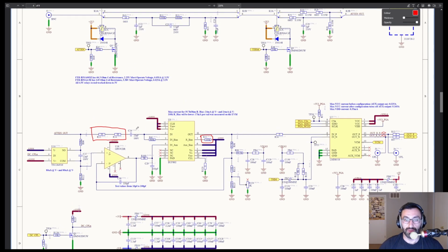Now you could basically keep stacking those, but the problem is eventually you run into the extra parasitics of having a bunch of those resistors. And if you use high value resistors, well, now you're burning a lot more power in those, and they have to be bigger in order to sustain that power rating. So it's all trade-offs, the whole way down.